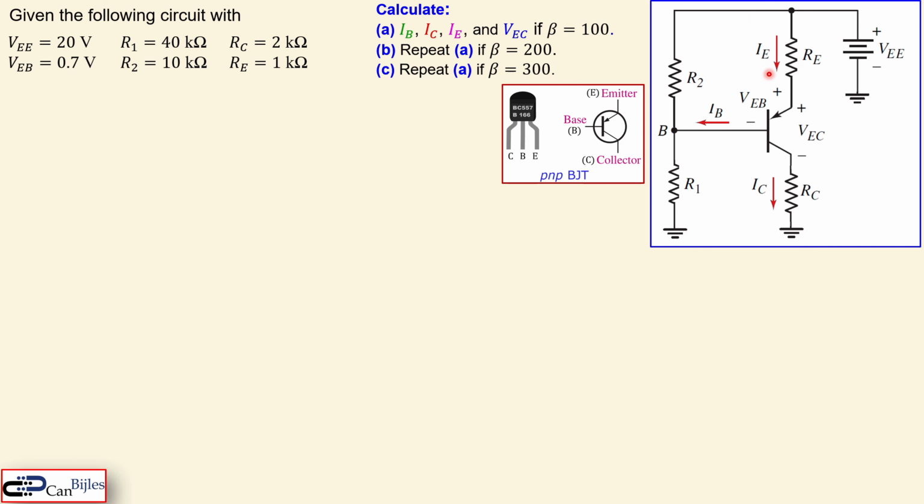We also see that the emitter current is now flowing in this branch, and the base current is flowing out, and also the collector current is flowing out. In fact, the emitter current is again the summation of the base current and the collector current. That is still valid, but it is in the reverse direction. And in this convenient version, the emitter is in the top branch and the collector is in the bottom branch, which was reversed for the NPN transistor. So that is briefly the discussion of the PNP compared to the NPN.